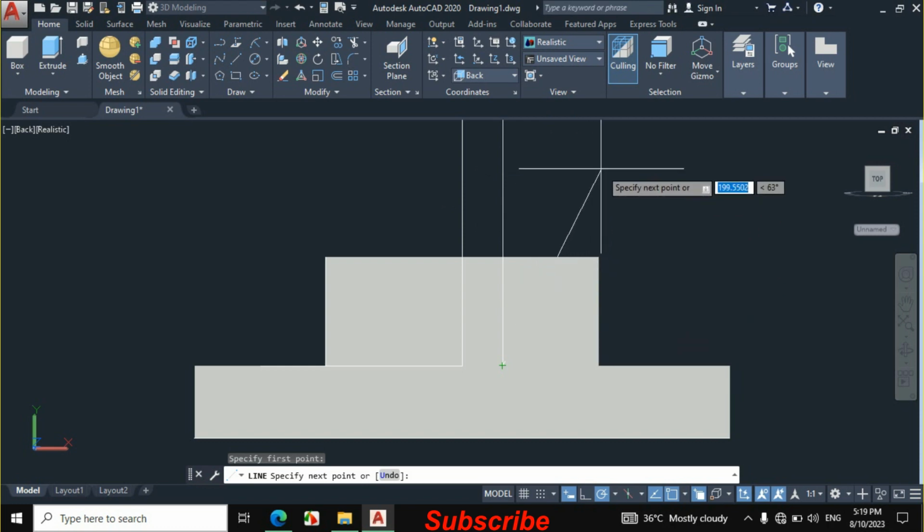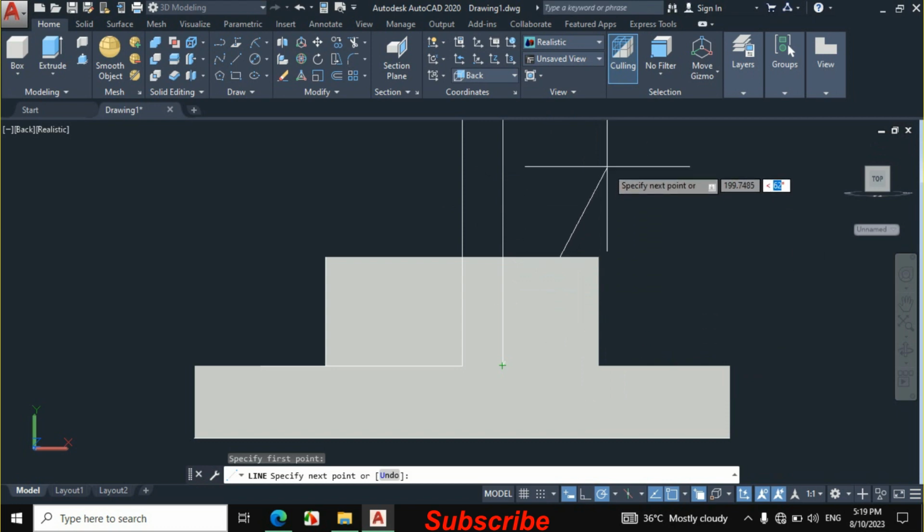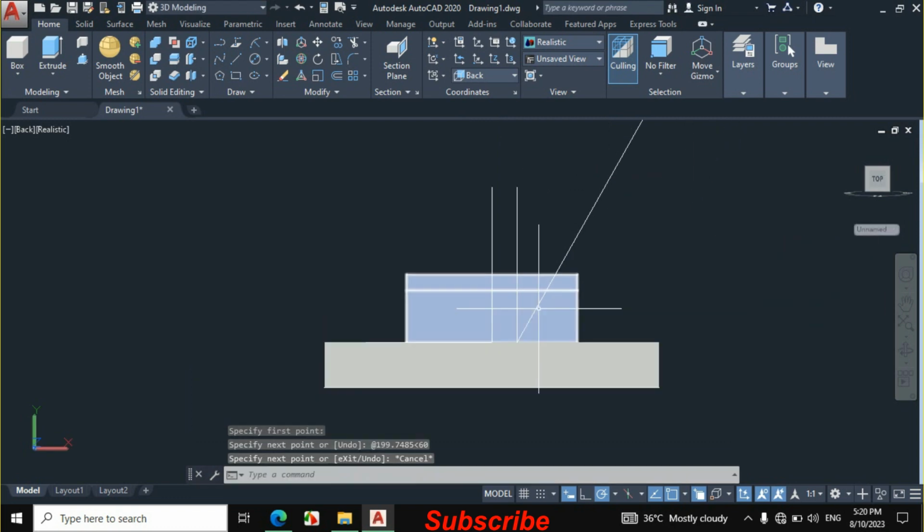So press tab for angle. Now we enter 60 degrees, because from this line to this line, this angle becomes 60 and this angle becomes 30, which is required. Then press enter and press escape.